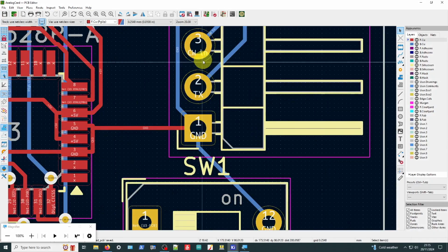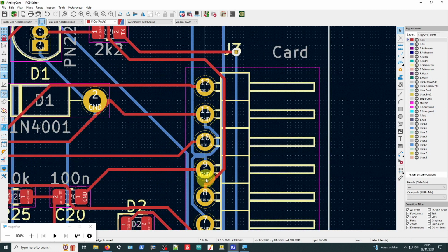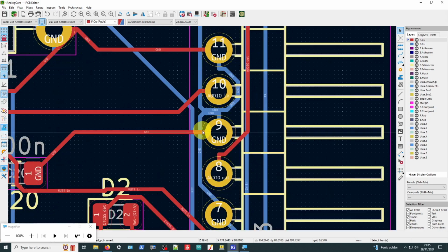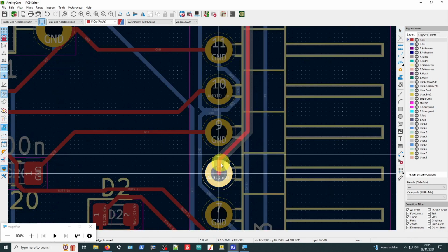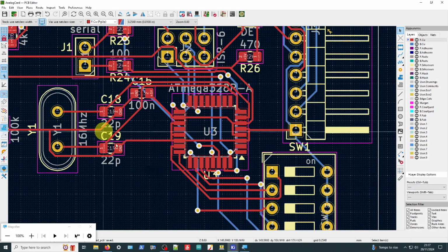at the bottom. So it's completely fine, because if you think about it, when you put the header into the board, you could have it pointing this way, you could have it pointing that way, you can orientate it any which way you want, and there aren't any markers on the header either. You just cut them off as a strip with your side cutters. So it's right to warn me that the footprint has changed. It's correct for it to tell me that, but at the same time it doesn't need to, because I've made it that way. I'm going to look at doing a copper fill. I think we're going to go away and do that right now.